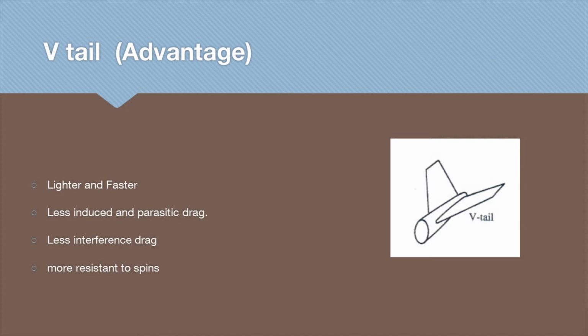However, according to the study done by the NACA, it indicates that the V-tail surface must be larger than the simple projection into the vertical and horizontal planes in order to get a similar performance. So actually, the total wetted area is roughly constant.